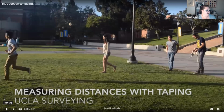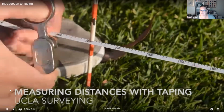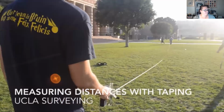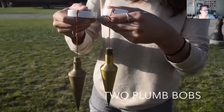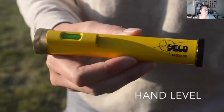To another UCLA surveying instructional video. Today, we will be measuring horizontal distances with taping. The process is easy to learn, but first we need a few pieces of equipment, such as steel tape and a tape clamp handle, 2 plumb bobs, a force gauge, pins to mark points, a hand level, and of course, your surveyors.